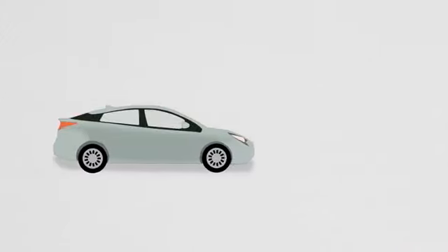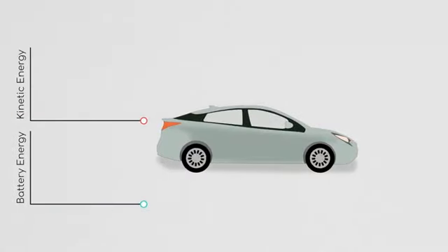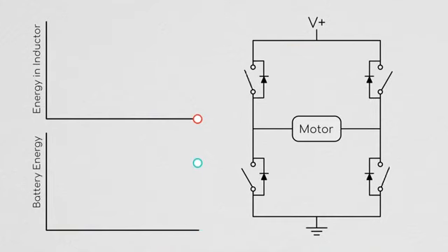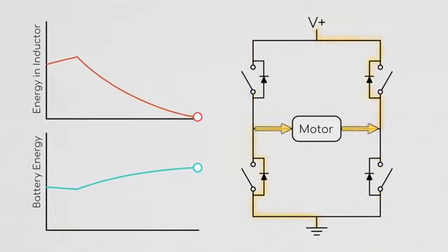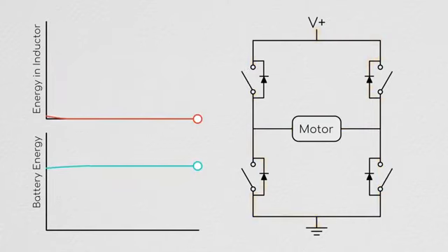For example, if we look at a car like a Prius or a Tesla using regenerative braking, the energy flowing back into the battery comes from reducing the car's kinetic energy as it slows to a stop. So, you're taking kinetic energy that you wanted to get rid of anyway and recapturing some portion of it. However, in the case of hard switching, the energy flowing back into your battery is energy your battery just spent trying to build the current up during the forced phase.